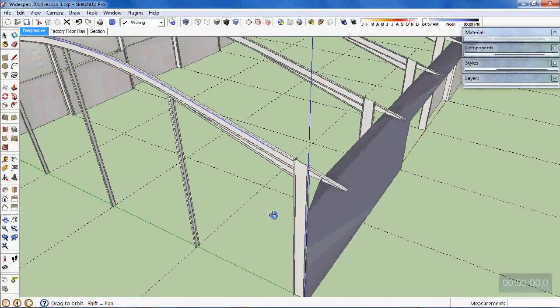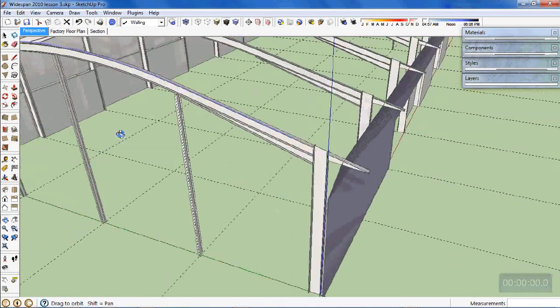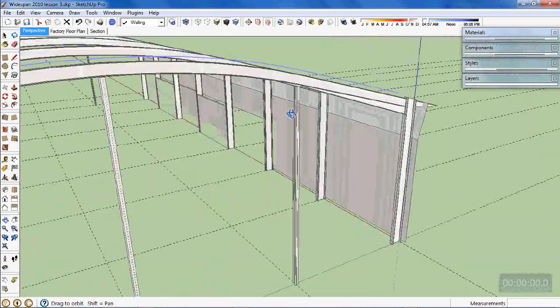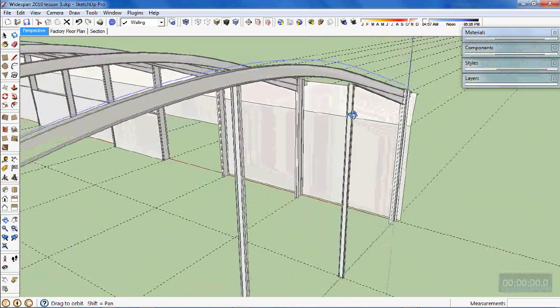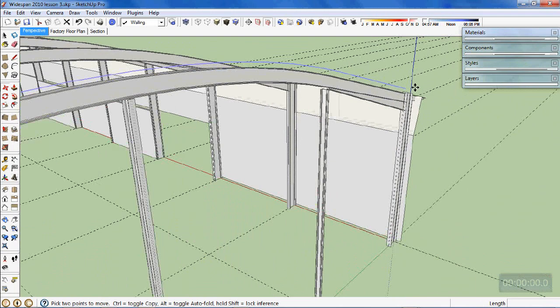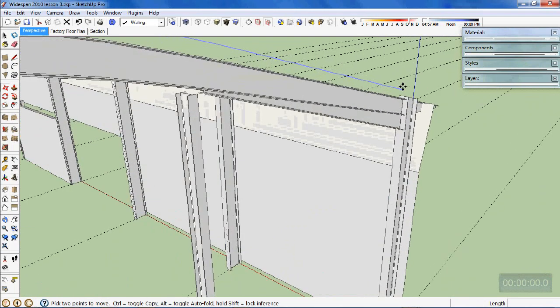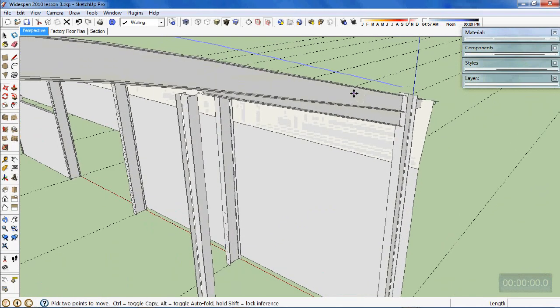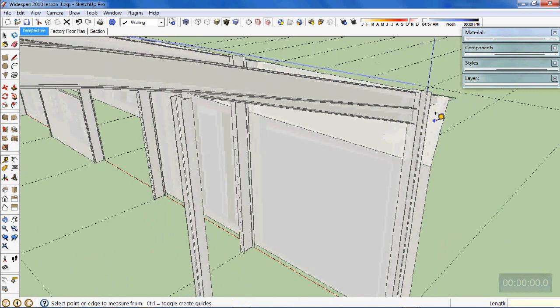Now, next little tricky point here. I'll just try this and see how I go first. I might actually, this would be the easiest way, pick up your tape measure, come off this line that we've created, come out and type 0. So we've created an extension to that, come onto this sloping edge through here, come off there and type 0.